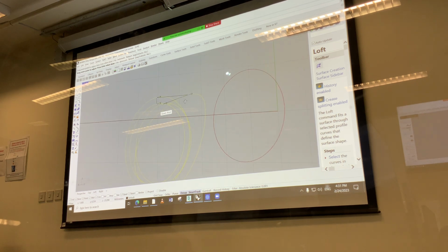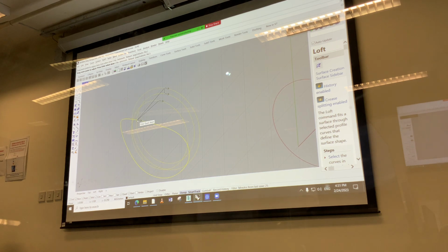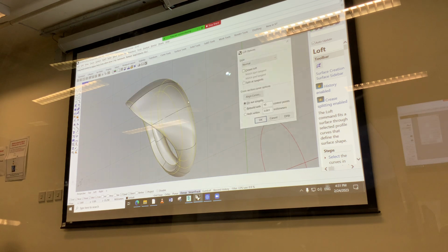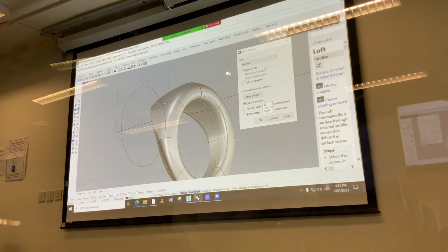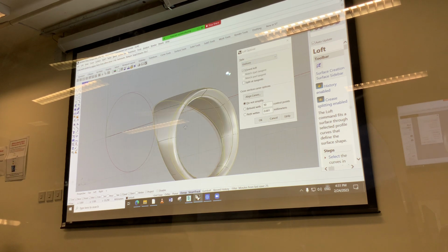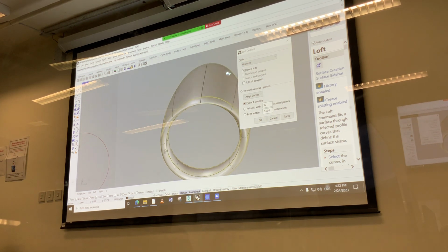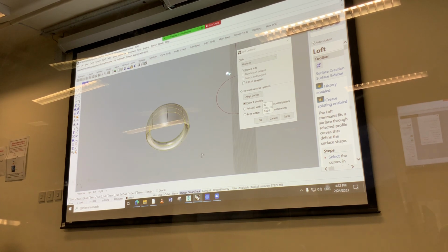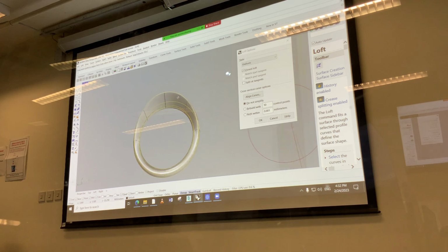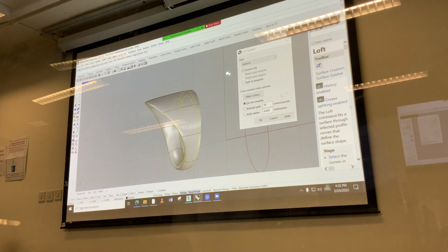See, I now very carefully made sure that the seam curves are where the knots are. One curve, there's a knot. So you have to use the quads of the knots. And then close the loft. And you see, if we then go to uniform, we get actually a very tight fit ring now already. Very clean design. No kind of wobbles anymore. None of that asymmetry, everything happier days.